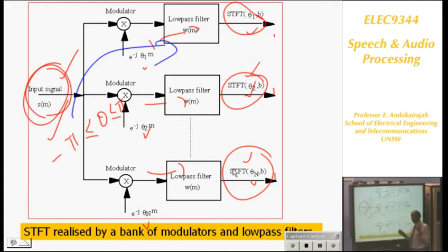This is the actual explanation of the short-time Fourier transform as a kind of bank of modulators, right? But when you implement this algorithm in MATLAB, you don't see it this way. This is not the way it's explained, just a simple algorithm. But the algorithm is based on this particular explanation, and you don't see it. But it's important to have an understanding of it. These low-pass filters, which are really the window size, really control the frequency resolution of the short-time Fourier transform.